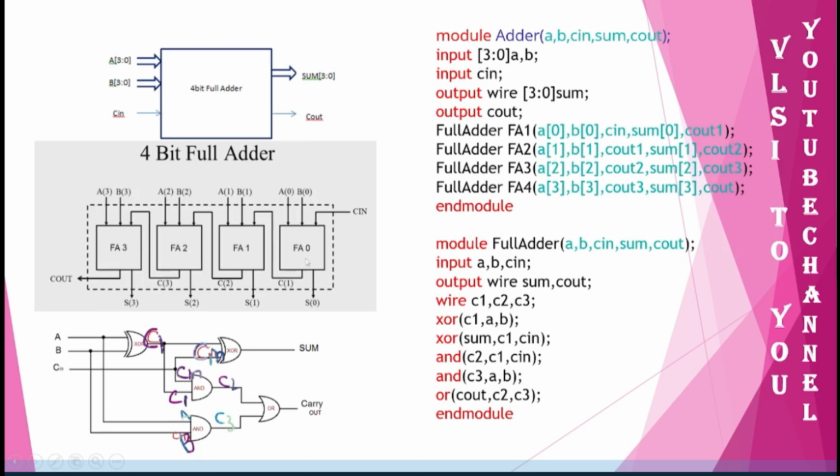Now you know that I need to have 4 full adders, so I am instantiating 4 full adders with 4 copies, FA0, FA1, FA2, FA3, basically FA1, FA2, FA3, FA4 if you consider, and now I am mentioning the connections. So this is my FA1. Okay, for this FA1, what are the inputs? A of 0, B of 0, and C in.